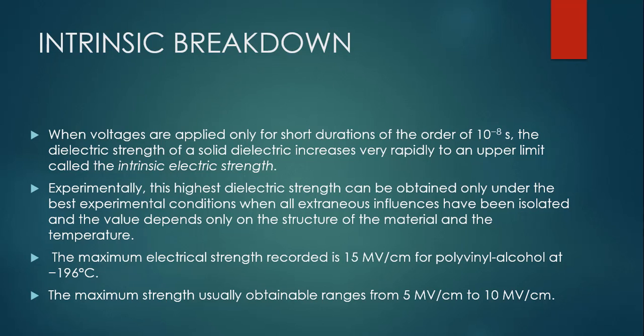The impurity atoms or molecules or both act as traps for the conduction electrons up to certain ranges of electric field and temperature. When these ranges are exceeded, the trapped electrons are released, and these electrons participate in the conduction process. Based on this principle, two types of intrinsic breakdown mechanism have been proposed.